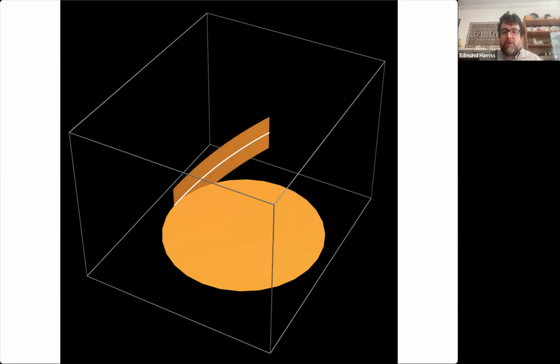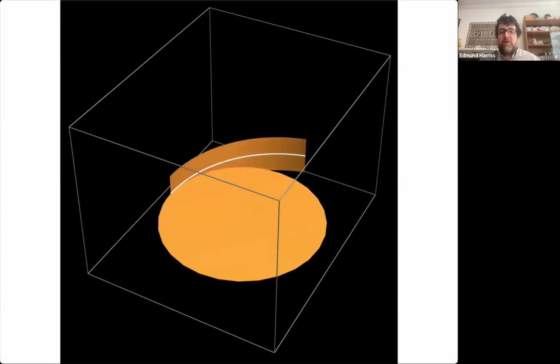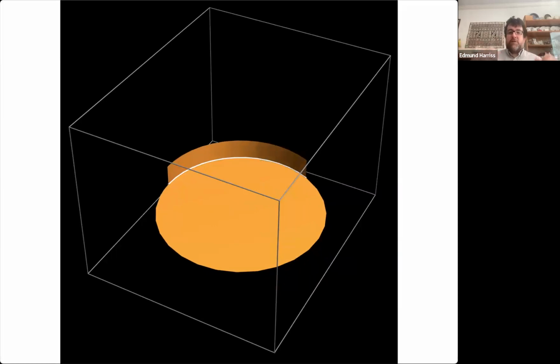And so here now you could basically have the idea that you can have a frame and you can bend one piece onto the other, and that top piece that's bending stays as a developable surface. It stays as flat as it bends round, because we're avoiding that twisting. So when you have that sort of torsion, that twisting, that changes the geometry. And so that's something that a strip of paper or a strip of metal can't do without having to stretch internally.